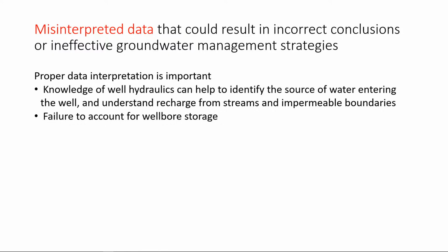So you need to account for this well storage, and one way to do this is to have your pumping well and an observation well, and the observation well would be at a distance that's not too far and not too close to your pumping well. That's one way to account for this.